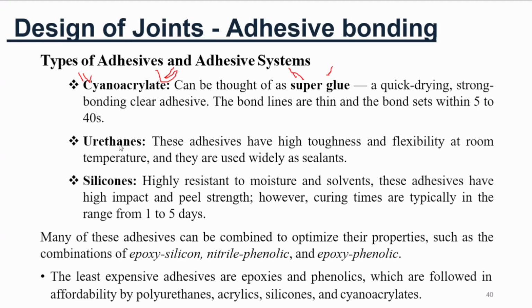So combination systems: some adhesives are blended to optimize properties. Epoxy silicones, nitrile phenolic, epoxy phenolic. Epoxy silicone combines strength with flexibility. Nitrile phenolic adds toughness and heat resistance.